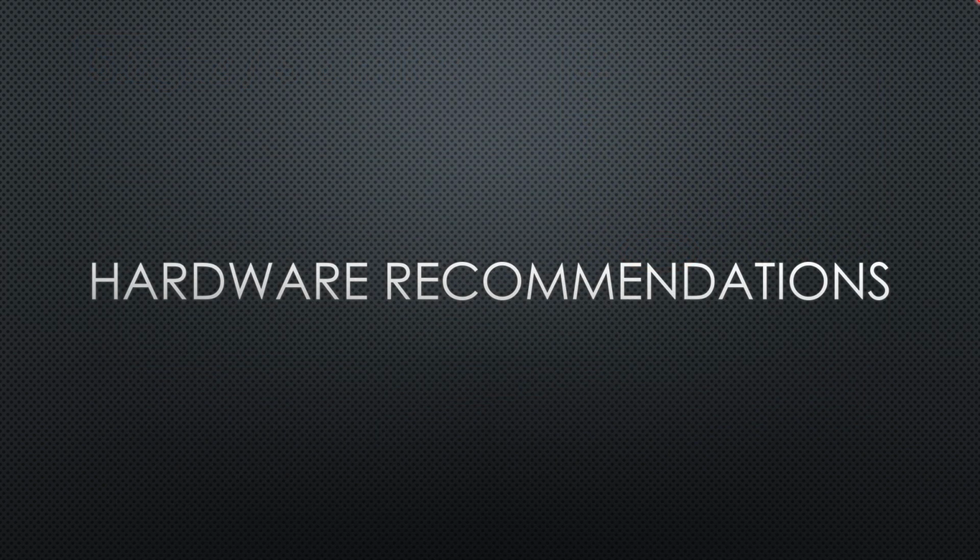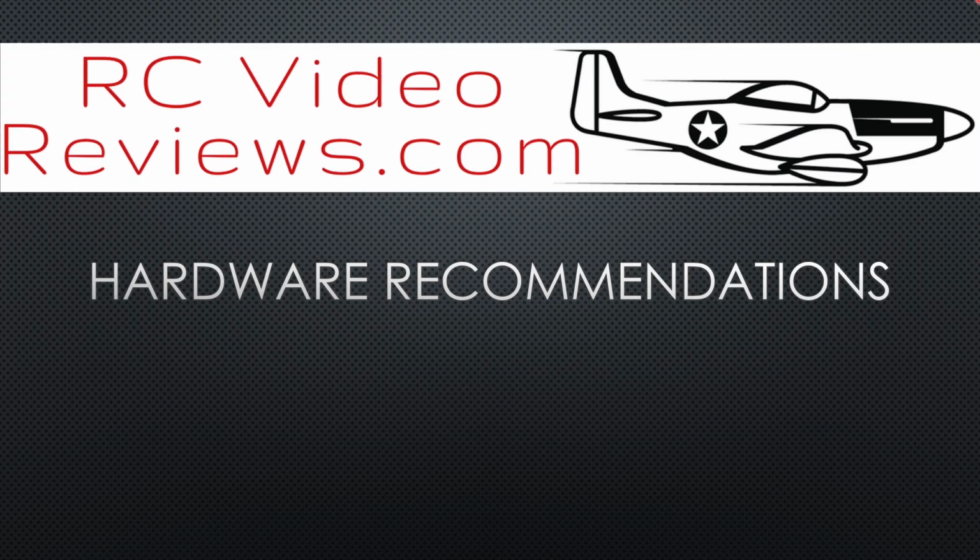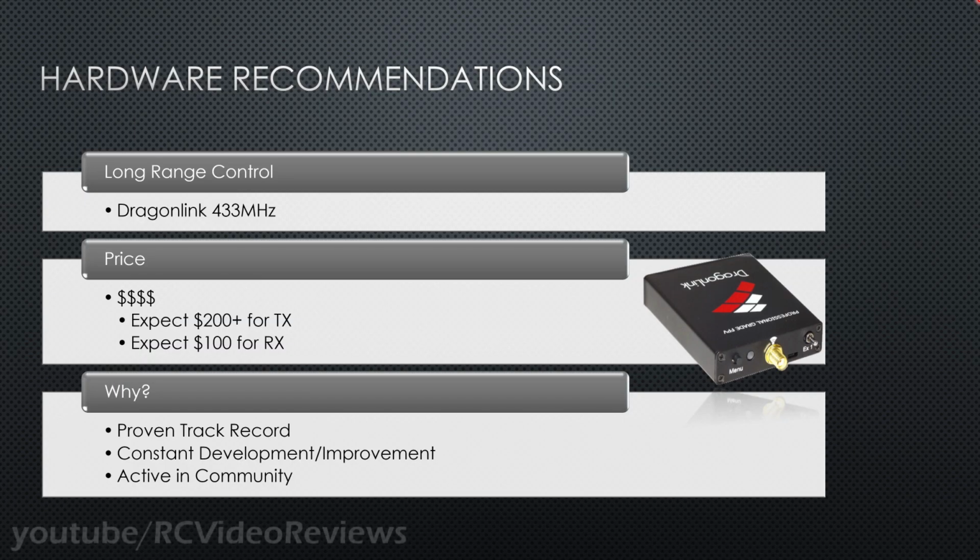Okay, next up are hardware recommendations. I thought what would be the point of going through all this if I didn't recommend some hardware at the end. First, I'll throw out the long-range control. I've personally used DragonLink, 433 megahertz. This stuff is not cheap. You can expect to pay around $200 for the transmitter and about $100 a pop per receiver.